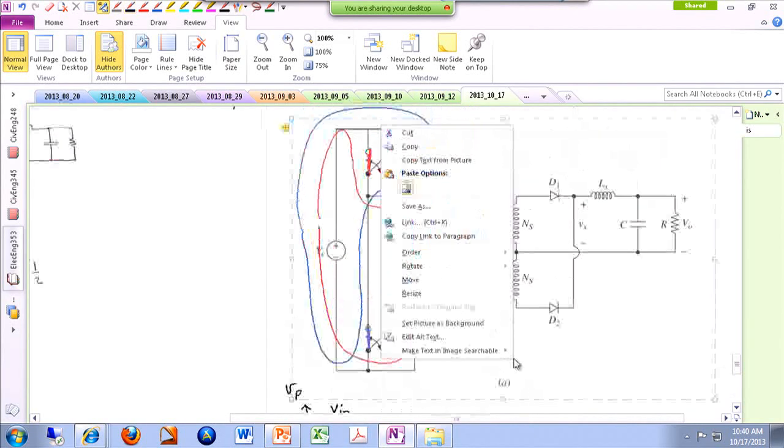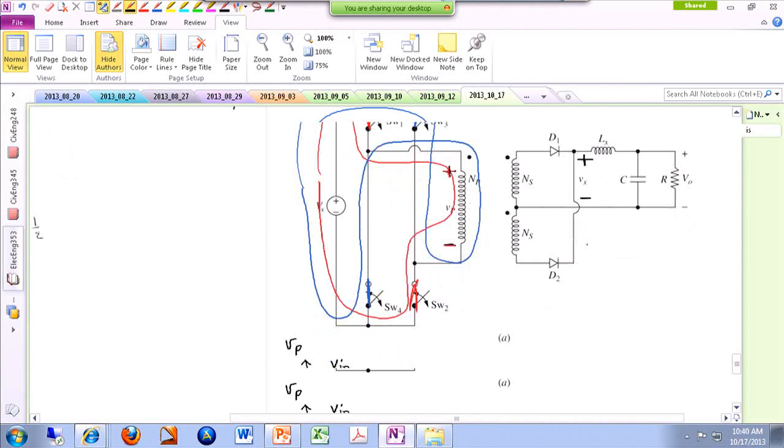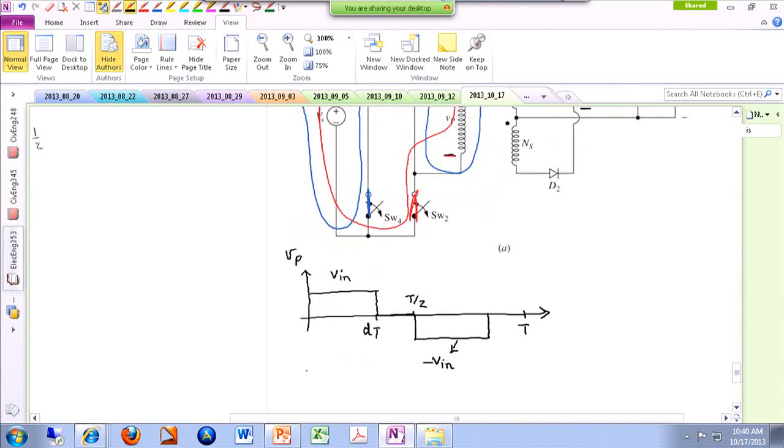So for instance, if you look at Vx over here, Vx is the rectified version of the signal multiplied by the turns ratio of the transformer. So if I just plot Vx, it is the same thing, only rectified.